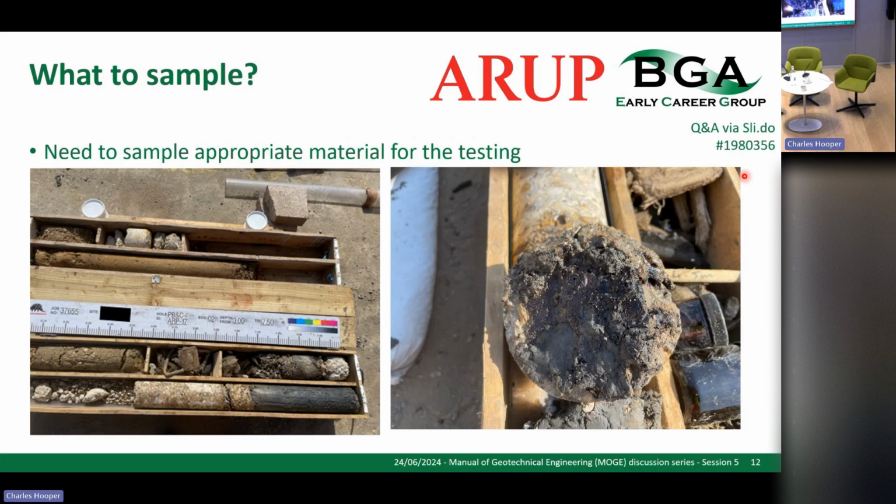Fortunately, not all things are quite so easy. In this particular example, we actually had about 7 meters of made ground, including 2 layers of concrete. About 3 meters and down at the 6 odd meters, again a deeper layer. So quite complicated. And then the infill material in the middle, part of it is a sandy sort of clay fill, but other parts you can see in the very middle, we've got metal, we've got wood. We haven't got great recovery, so we can't take our samples in this really, and this is a challenge that you won't always be able to apply that rule of thumb.